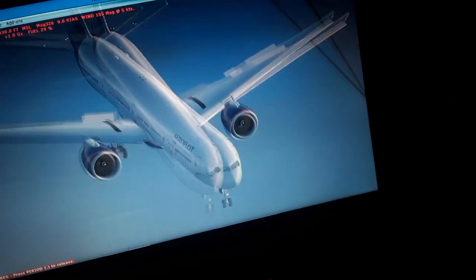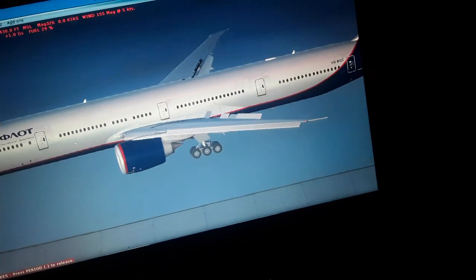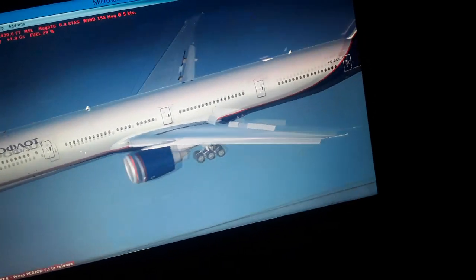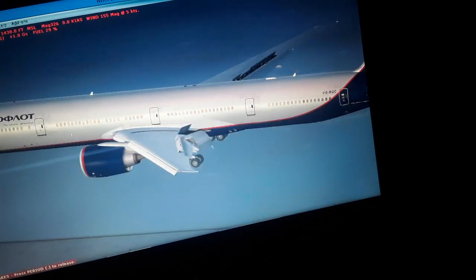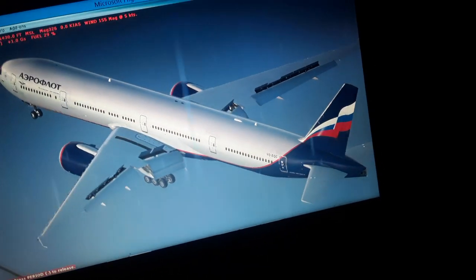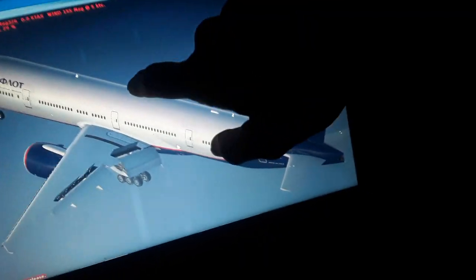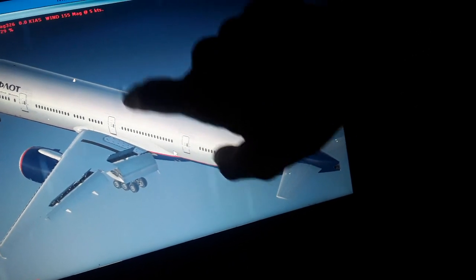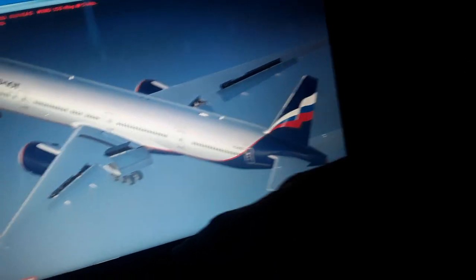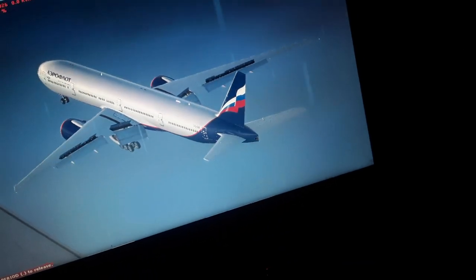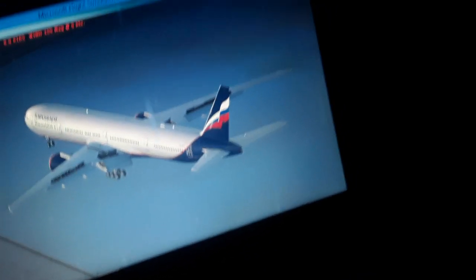So the wings of the airplane stall at this position. You make the aircraft lose its lift from its wings. So it's also the position where you place the center of gravity of the airplane. You can place it forward or aft by moving the cargo and the passengers inside the aircraft.